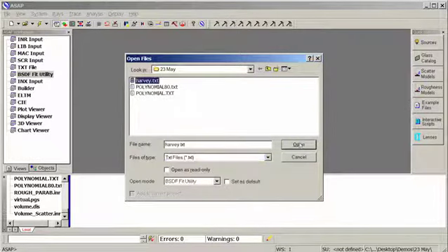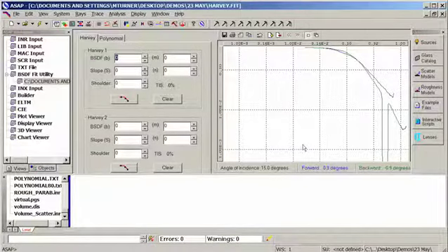In particular, the first thing we'll look at is a Harvey fit. This will fit to what's referred to as a Harvey polynomial. That's defined by its maximum value, where its shoulder occurs, and where the slope is. There are two ways in particular. You can ask ASAP to fit automatically, or you can do the fit yourself.